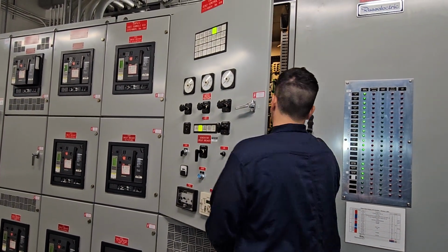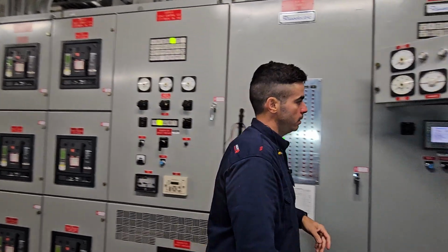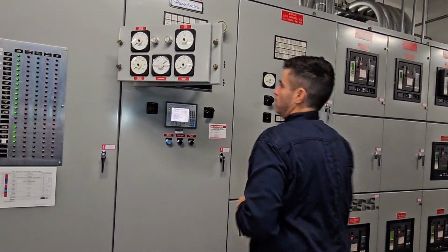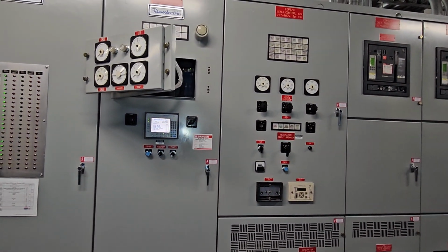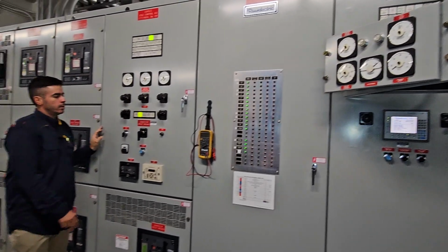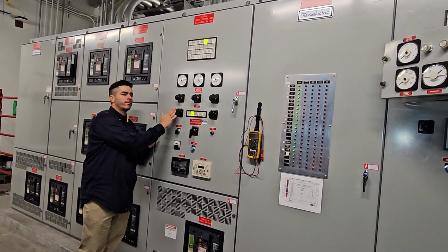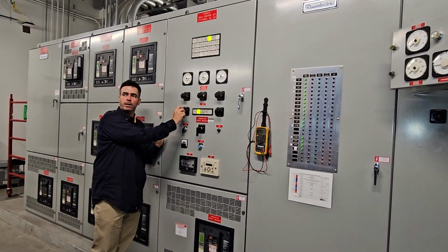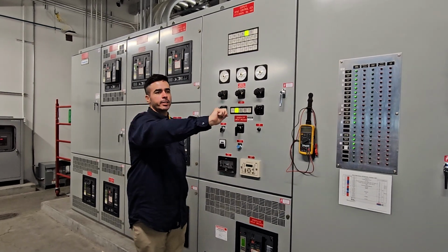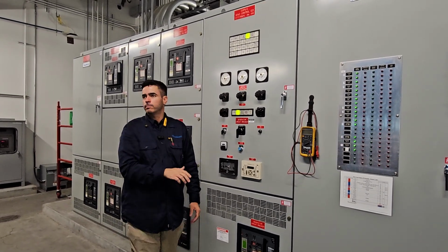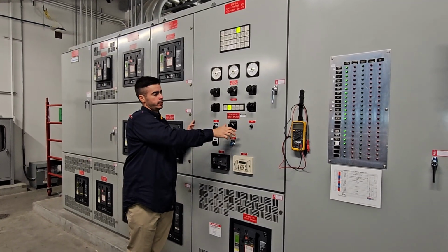We're gonna do an automatic operation for generator 2. So the engine is in the run position. If I try to close the breaker here, it shouldn't let me, because one of the conditions is to have this synchronoscope on. The reason is that we don't want anybody to have the chance to attempt a closing operation without really paying attention to what we're doing, right? So if I try, it's not doing it.